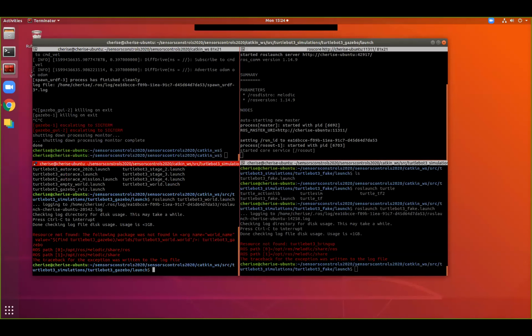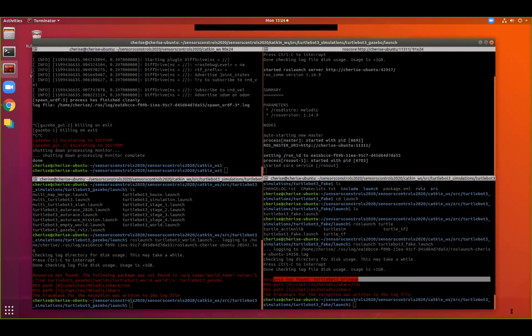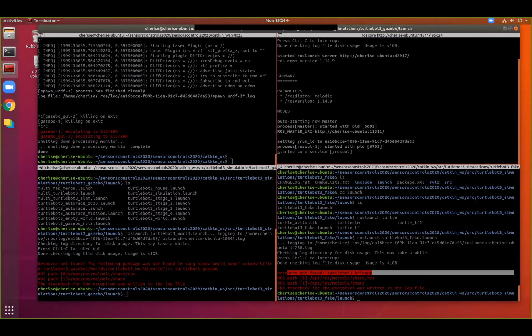Okay. So what I did is I followed all of the steps in the PDF document for the Gazebo simulation setup guide. Initially I was able to open the TurtleBot in the empty world. Then I was trying to open up the teleop things, and I was getting an error saying the resource isn't found, and now nothing opens. So I redid my catkin_make, and I did my source devel/setup.bash and made sure that's all good. But I've kind of run out of ideas.